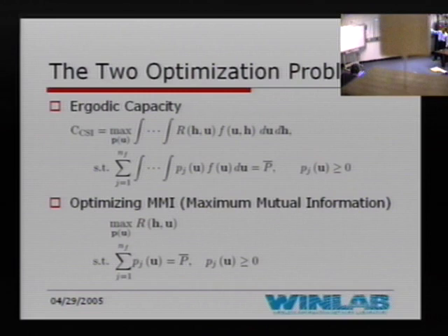Since I average over the distribution, I will see the channel at each time instant and see what value it takes, and wait for a very long time so that all those possible channel realizations occur. And if I get a bad channel, I might not transmit at all and keep on waiting until I get a very good channel to put my power.